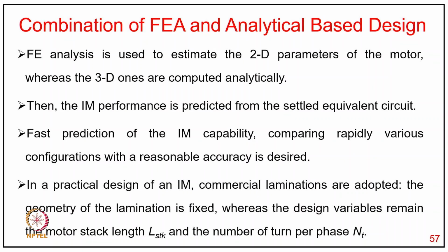Coming now to a combination of finite element and analytical based design. Finite element is used to estimate the 2D parameters of the motor, where the 3D ones are computed analytically. Then the induction motor performance is predicted from the settled equivalent circuit. Fast prediction of induction motor capability, to compare various configurations rapidly with reasonable accuracy, is desired. In a practical design of an induction motor, commercial laminations are adopted and the lamination geometry is fixed, so the design variables remain the motor stack length and the number of turns per phase.